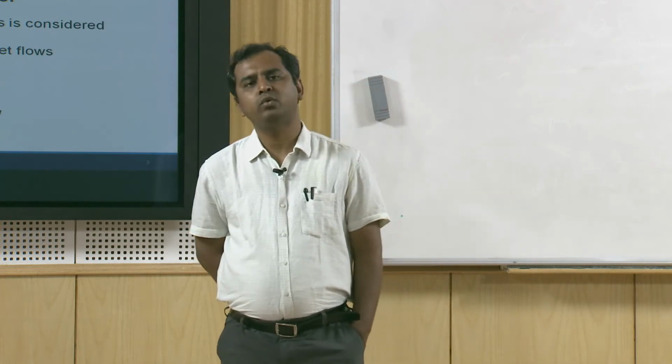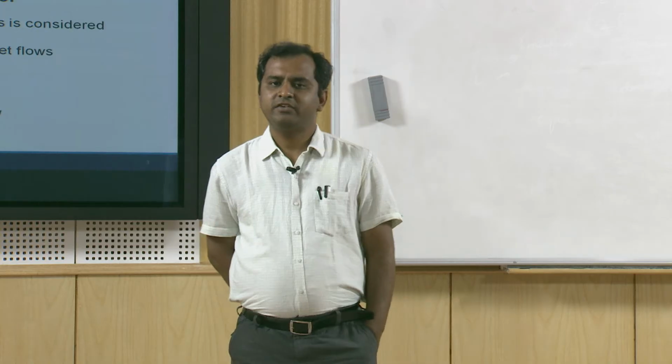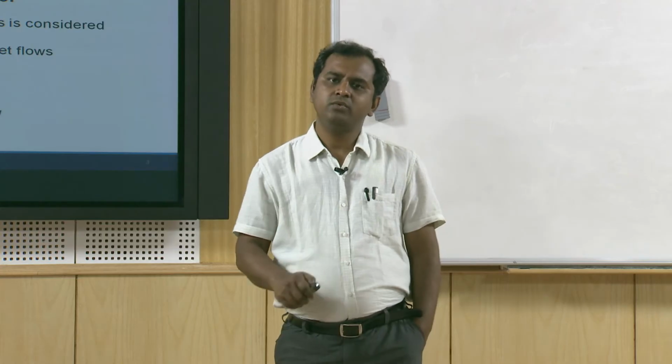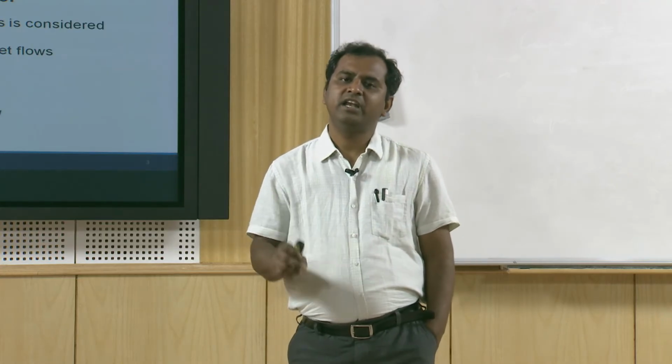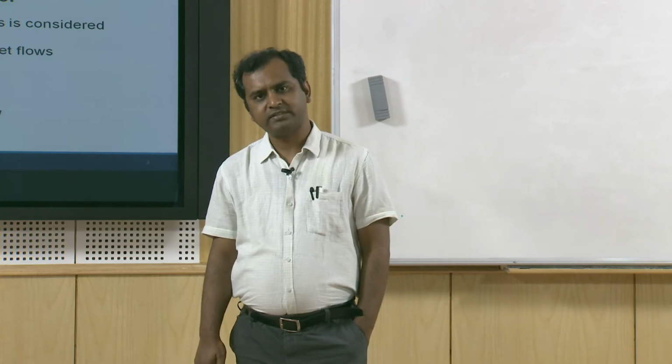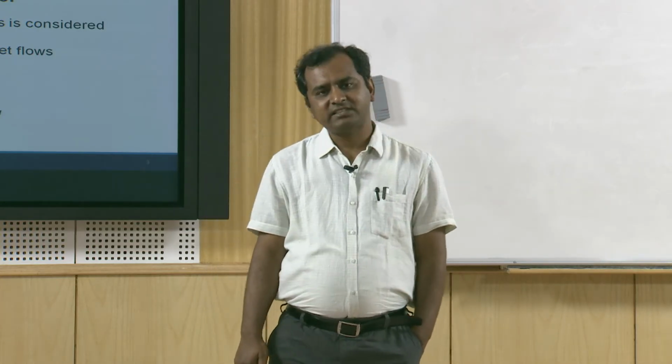Now, as there are two different velocities, ideally we should consider two separate sets of equations. That means, in case of adiabatic flow, two continuity equations and two momentum equations, and whenever we take heat transfer into consideration, we will have two energy equations also. But in the drift flux model, we are considering not only the individual phases, we are considering the relative motion. Once again we make a mixture kind of assumption for both the phases, and we are interested in the gas relative velocity.